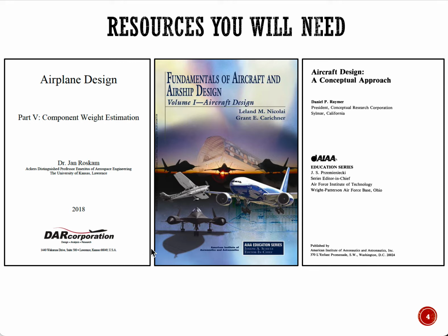VN diagram, right? Throughout the series of these videos, I mentioned the chapter and the page numbers where you can immediately go and take a look, to get the equations and the relevant steps you need to take to finish the component weight estimation and do other things like CG and VN diagram estimations, right?